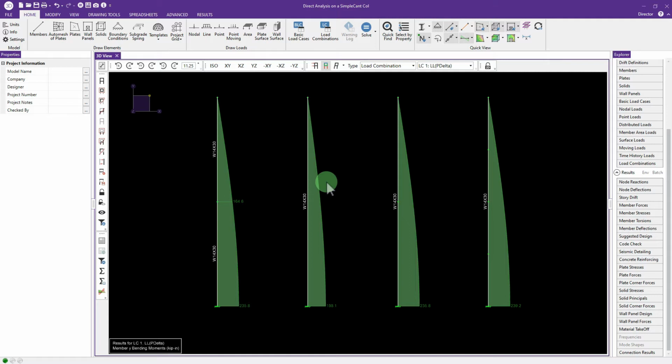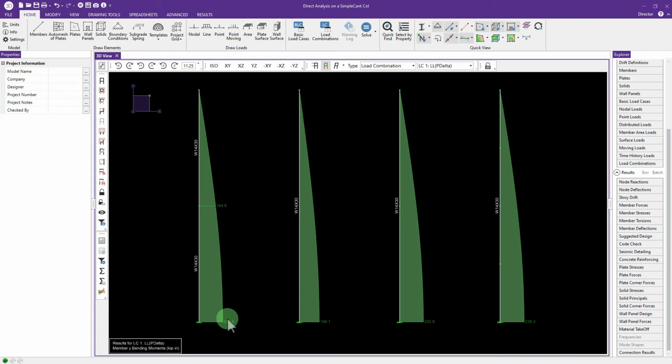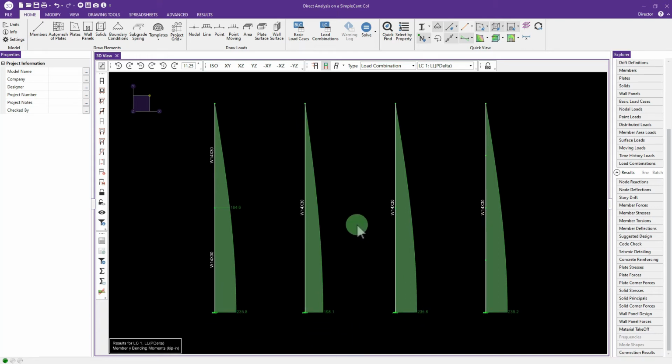Anything that you're going to rely on, any one of these things that are really like moment frames, you want to break it into at a minimum two pieces, all right, in order to get a more accurate bending moment from the analysis. Even as it's broken into individuals, you can see number one matches number three. Exactly. It is the exact same thing as far as the analysis, and as far as the computer is concerned. All right. Only difference is when you do the design, and I'll show you about that.